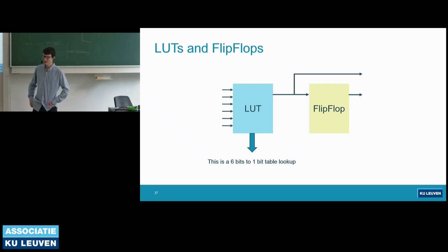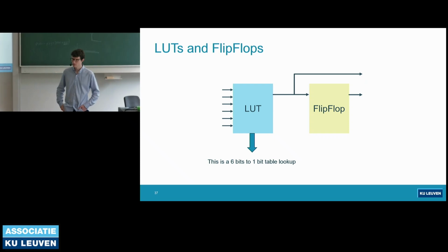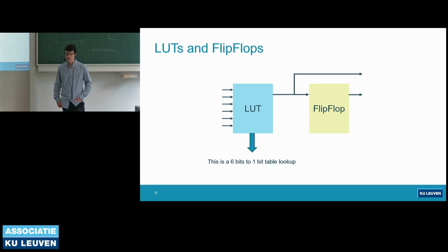Yes? What's the result of the 6-bit LUT thing? So 6-bit LUTs will give you 49 LUTs. And for LUT 4s, it will give you slightly more. It will get you 83. I don't have that, like the results for something more. OK, then I will change that, thank you. That's fair. Yeah, I should mention that is for LUT 6. That's for LUT 6 on the Xilinx FPGA, and I know that very few people here care, but it's for an Artix 7. So yeah, 7 series.